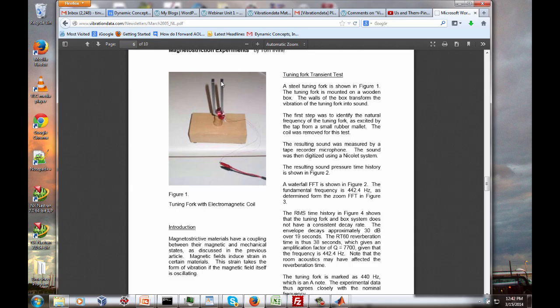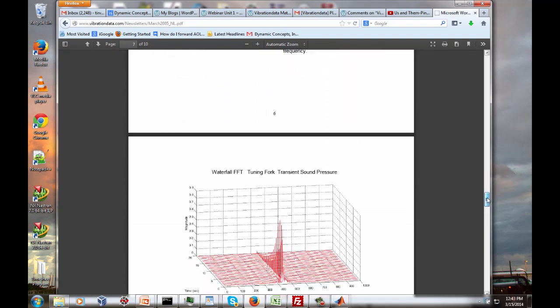And of course, due to manufacturing tolerances and so on, it wasn't exactly 440 hertz. So in order to excite this into a resonant response, I had to dial in on my analog function generator 1/2 that frequency, so 221.2 hertz. That's what I dialed in, and I applied that voltage signal, or you could say that current signal, to excite the tuning fork into its resonant vibration.